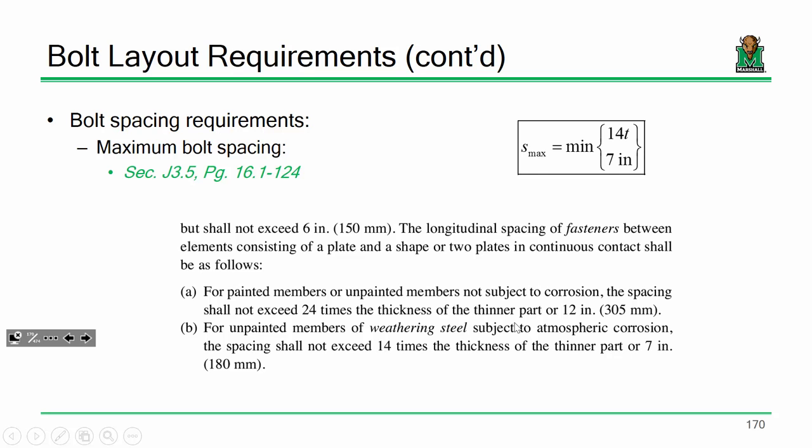Sandwich them together, right? So what happens if those bolts get too far apart is those plates don't really want to sandwich together, and you might have a little bit of a gap in between those plates. What do you think can get into that gap right there? Water, all right? And if water gets into that gap, what's going to happen? Well, you got water in contact with metal, and what does metal like to do when it's in contact with water? It likes to rust, yeah.